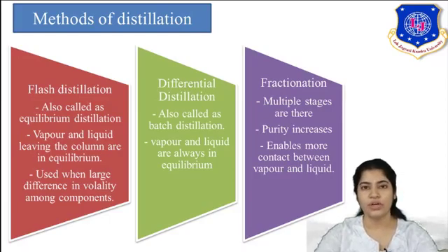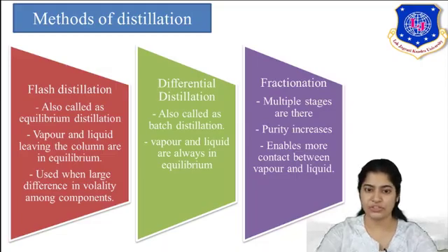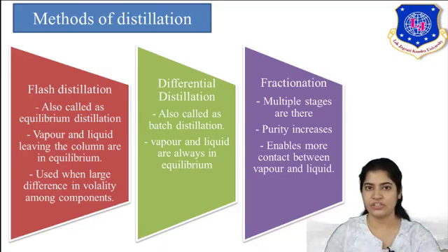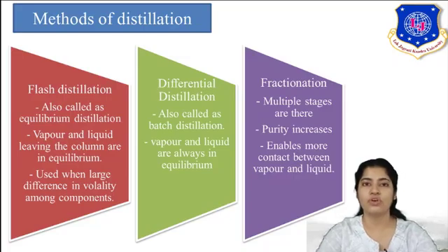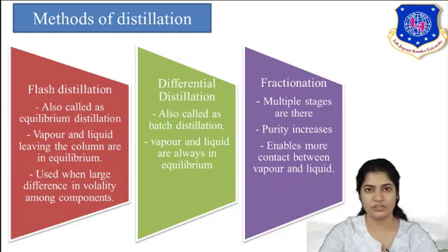What is the significance of fractionation? It helps to increase the purity of the product. It is a series of multiple stages, and with each passing stage your purity increases, because it enables more contact between vapor and liquid. So this was about the methods of distillation.